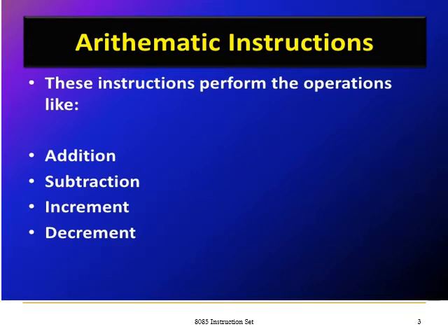Good morning students. In the previous video lecture, we have discussed the data transfer instructions available in the 8085 microprocessor. In today's video lecture, we will see the arithmetic and logical instructions available in the 8085 microprocessor. Arithmetic instructions perform operations like addition, subtraction, increment and decrement. Let us see the arithmetic instructions one by one.